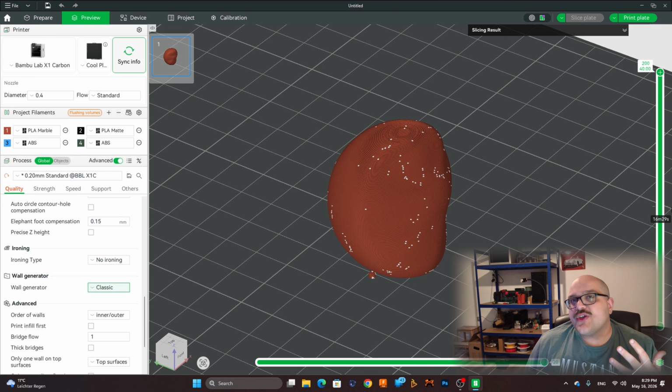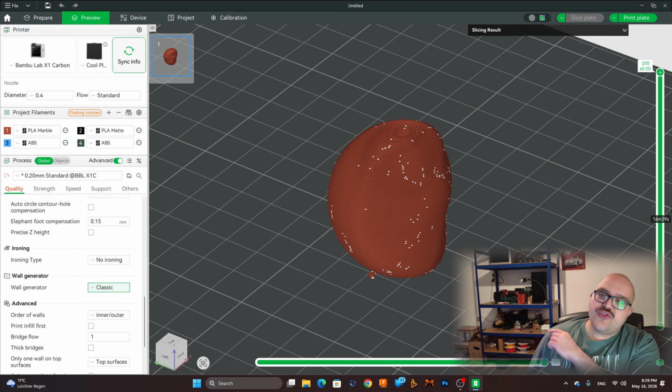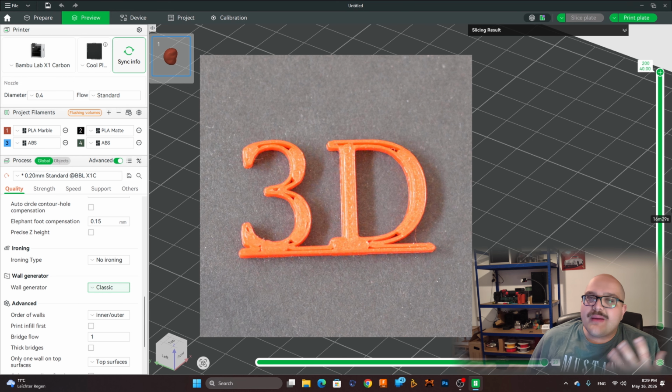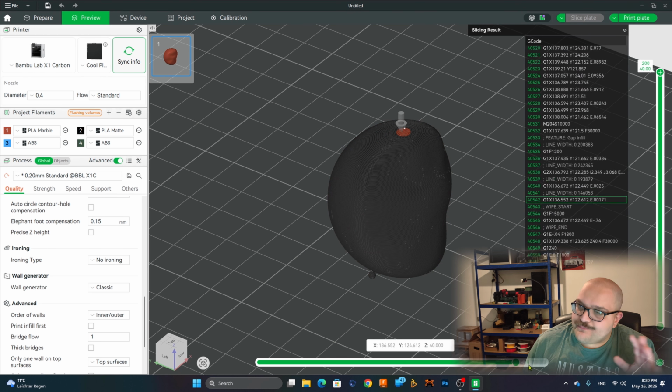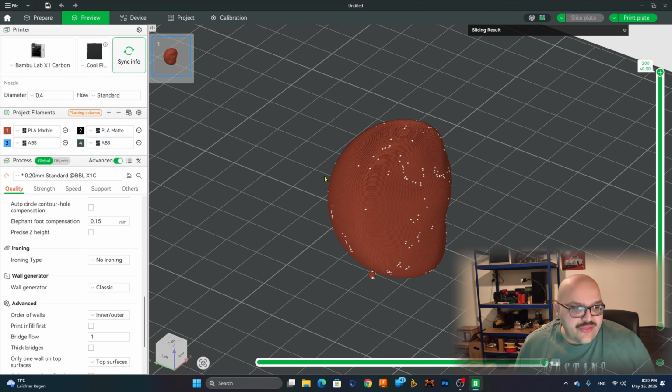Now, the problem with introducing those gaps, and once again you see them right there, is that sometimes they are just aesthetic problems. But fundamentally speaking, if you're introducing gaps inside the actual structure of your item, you may be introducing mechanical failure points that you didn't account for, that you didn't even think about. So it's a good idea when you are designing an item, especially if it's something functional, to take into consideration all those small details. You don't really have to look at any other thing.